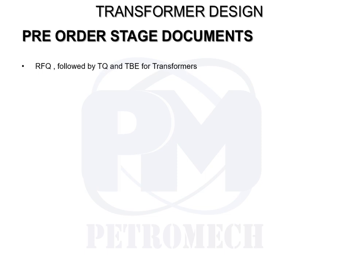Once we receive the technical quotations, they include a lot of technical data which are pre-filled by the vendor. Some data may not be submitted by the vendor during the offer stage, which we have to clarify with the vendor. If it is eventually required and may have cost or design impact later on, we have to ask for those data and get them clarified in the pre-order stage itself. And some data can only be furnished after the transformer design by the manufacturer, so those data have to be parked for the post-order stage.